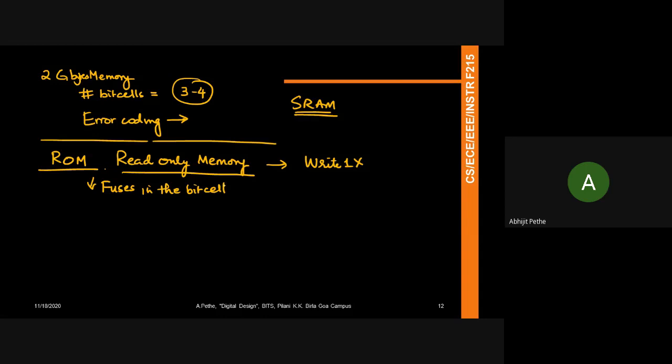In that sense, it continues to function as read only. You write it only once and then reuse what is written into it many times for your applications. Later, suppose you want to reuse the chip, you come in with a blank erase, erase the entire memory, rewrite into it, and then use it again.